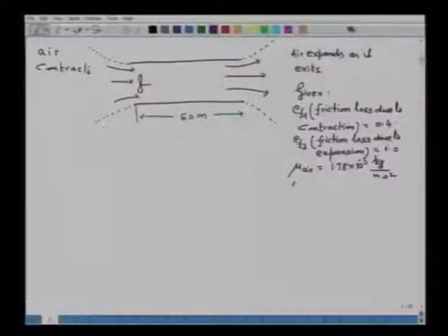Also, in solving these particular problems, many a times the conversion factors are also important. So, it is given here, say 1 millimeter mercury is equal to 133.2 Newton per meter square. Now we have to find out what should be the capacity of the fan.